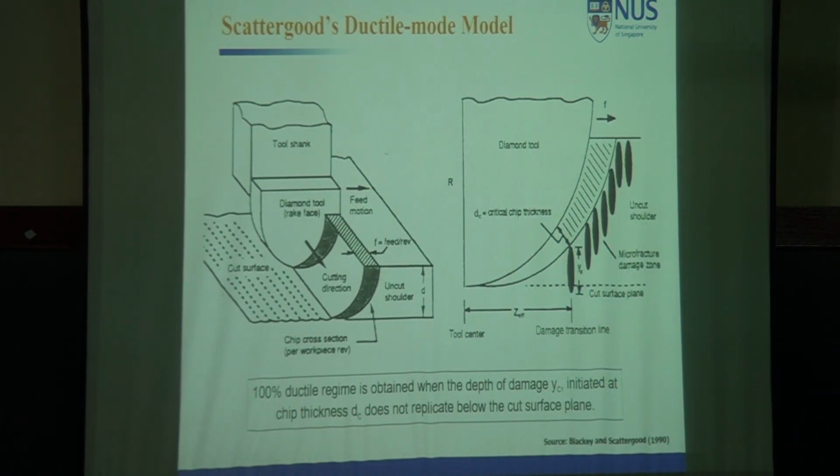depth of cut. They did not know that there is a value which is the critical chip thickness, but we finally found it in a paper. And for silicon, that critical chip thickness is 1 micron. For tungsten, it is 3.5 micron. So they machined silicon, and at that point